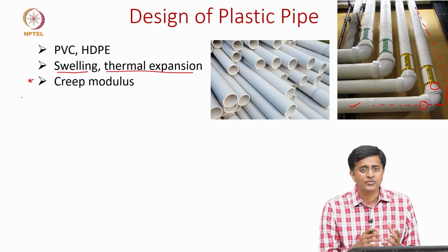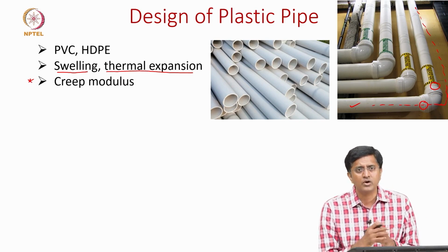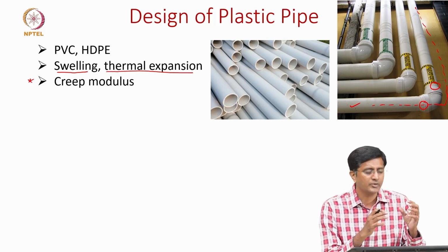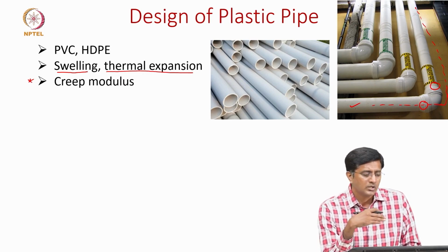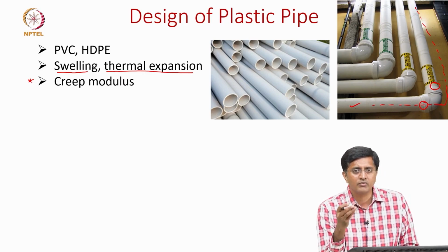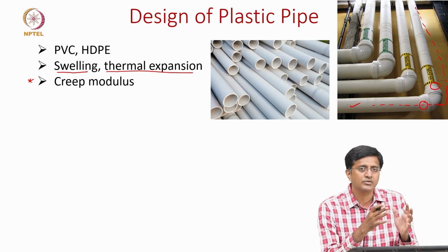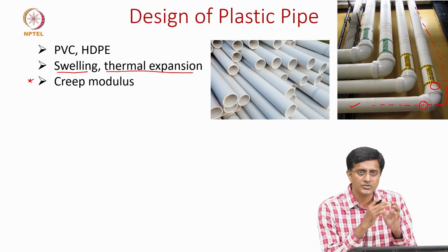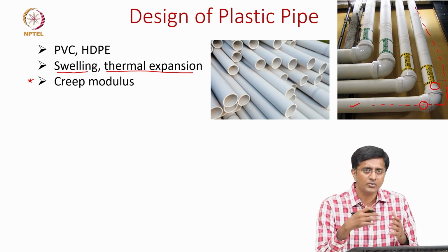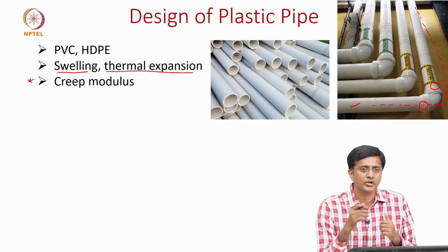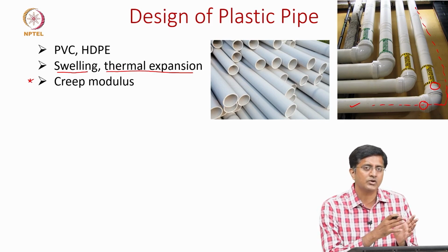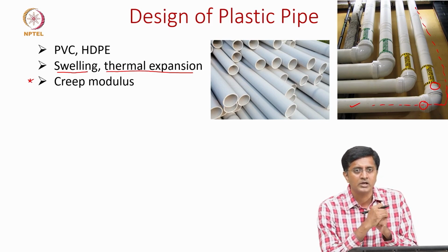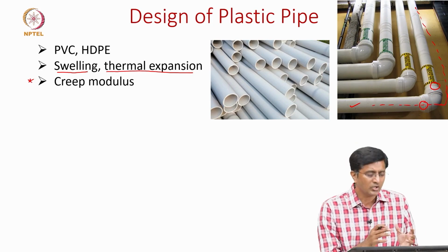So, depending on the kind of loads, as we all know, the creep modulus changes with time. Initially, it might start with a high creep modulus, but over time the modulus values decrease. So, depending on the loading, whether you are looking at short periods of time, then you look at the short term creep modulus, but if you are looking at long periods of time, of course then we look at the long term or the equilibrium creep modulus. But depending again on whether these are seismic loads or whether these are occasional loads, it all depends.